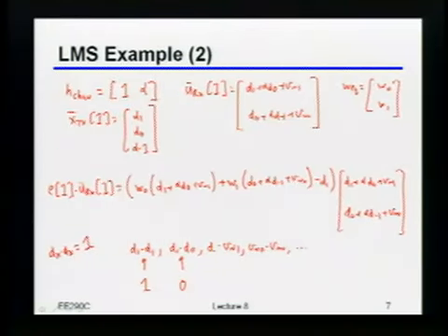Because assuming that D0 and D1 have nothing to do with each other, then half of the time 1 times 1 would give you 1, -1 times -1 would also give you 1. But of course, on the other half of the time, the signs are flipped. So on average, when I add those things together, I should just get 0, which is just another fancy way of saying, as long as D1 and D0 are uncorrelated, that'll just get knocked off by the filter, right?